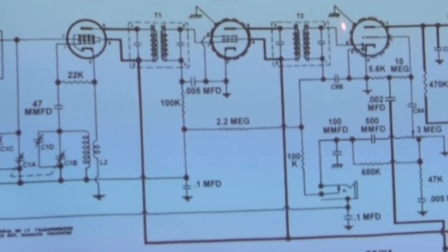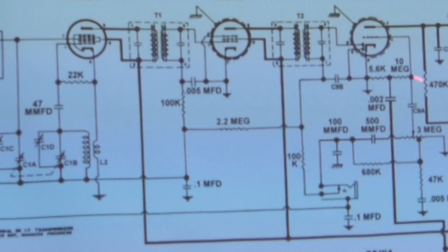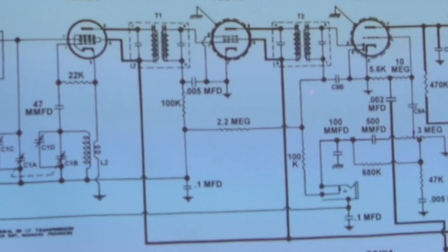Okay, we're up here, and we've got our detection in place. Comes down there. That's about 100 picofarads. Sometimes it goes as high as 200 picofarads, but if it goes higher than that, you start to shunt your audio portion to ground. You don't want that. And this side of it is ground. In the 12AT6, you notice that one diode is also grounded. Sometimes they just bridge them together, and you got both diodes paralleled, coupled. Other times they might pass one of the diodes to some other part of the circuit, but you don't have to worry about the details there. The idea is that you have your detection in place.